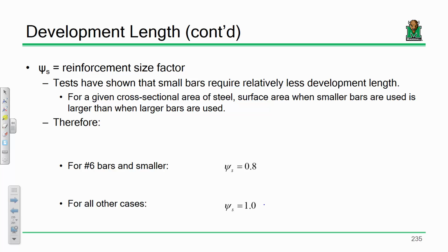This one's really wild. This one's kind of interesting. All right, I'm gonna throw you for a loop a little bit. Okay. Remember when we were designing reinforced concrete beams and we said, okay, you need an area of steel required of like 3.4 square inches, right? You know that because there's only so many multiples of rebar that fit within a given beam, we've set up until now to use the minimum amount of bars possible, right?